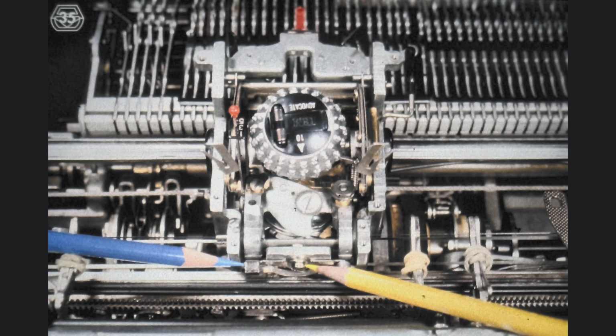However, at the point indicated by the yellow pencil, the bracket has a slot allowing vertical adjustment of the rear of the carrier. It is important that the height of the carrier be positioned in such a way that the escapement pawl becomes centered with the escapement rack. The height of the engagement of the escapement pawl with the escapement rack is easily visible when you observe the escapement pawl through the right side of the power frame. Again, be sure not to leave any binds in the carrier whenever you have to change this adjustment on any machine. It will cause character crowding or piling.